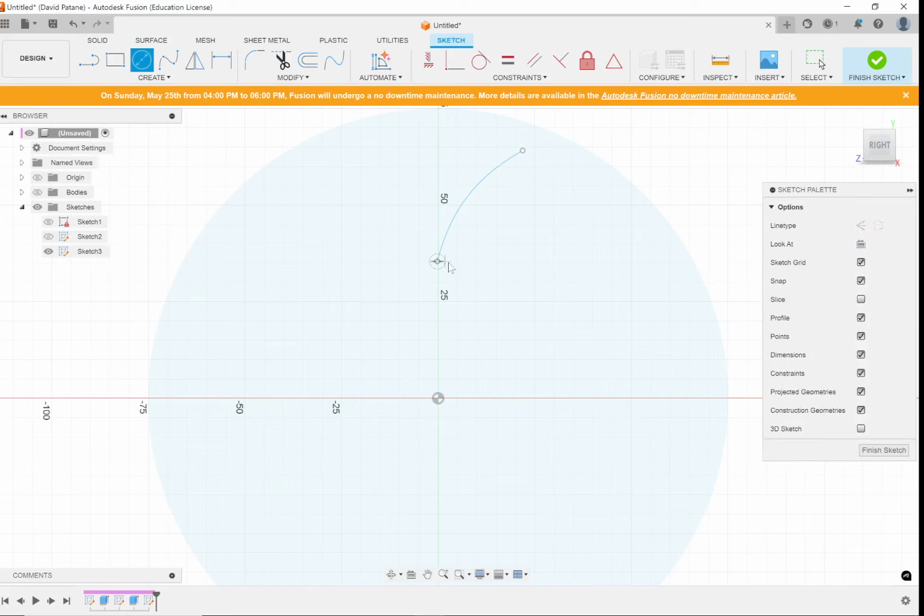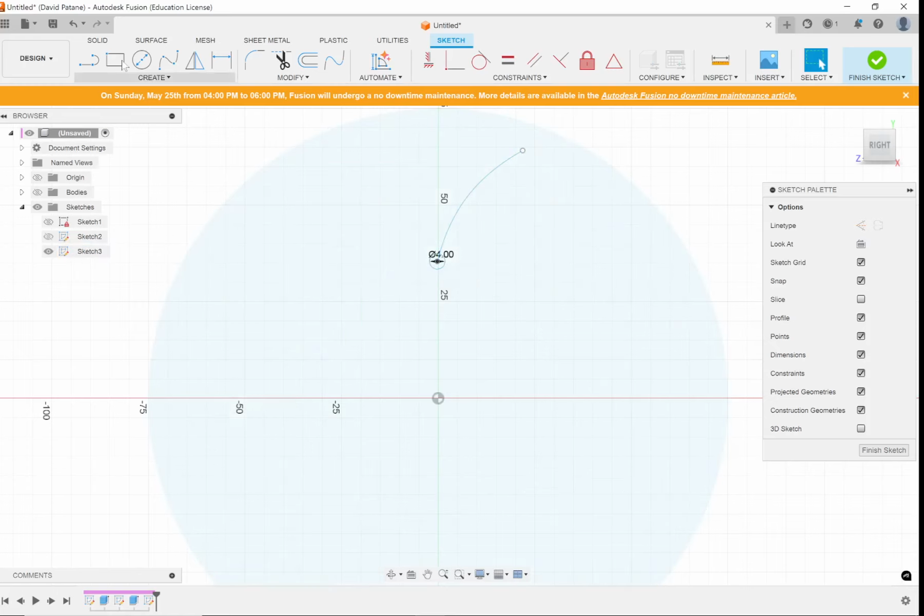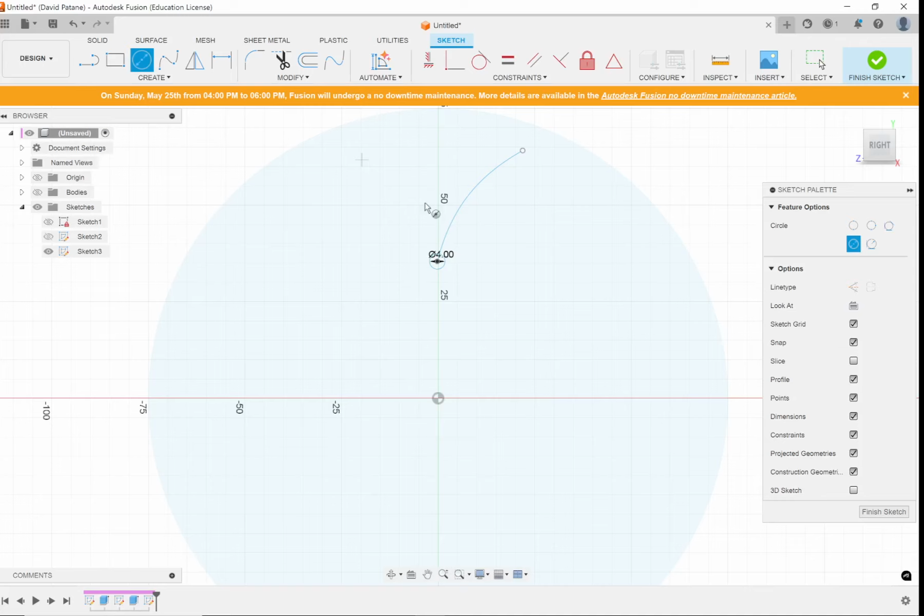I want this hole to be 4 millimeters, and so now I have this hole here. Now I can just draw this hole along this path. CAD allows me, if that's a good path, I can make a new circle. As I bring my mouse to the circle, it changes the symbol. So that means in this CAD software, it's saying your next circle, I want it to follow that line. So good if you have a particular constraint.